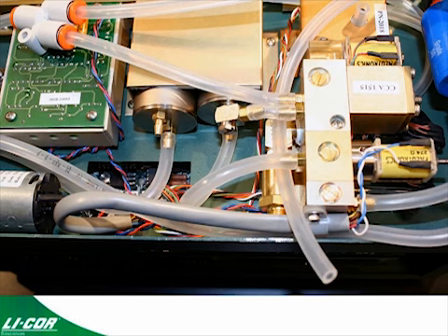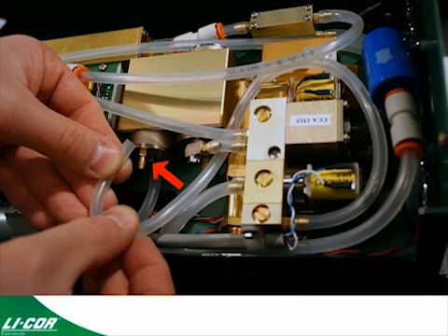Attach the new tube number 4 to the outlet side of the CO2 mixer as shown here, and then the final connection is to take the new tube number 3 and connect it to the upper barb on the first buffer volume. You do this by gently forming a bend in the tube to connect it to the barb. Be careful not to overbend the tube and damage that tube, restricting the flow.